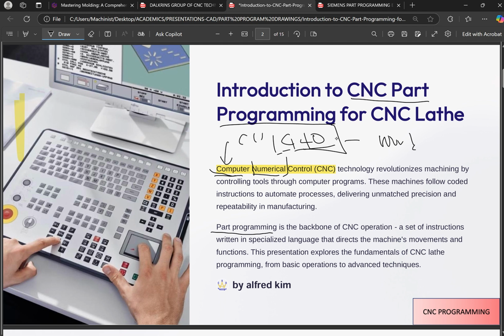Normally there is what is called the part program, which means you program a single component. If you have many parts together, you program a single component to give you that part. So that after machining the many parts, you can assemble them to give you an assemblage or sub-assemblies of the parts. So when you say part program, you are creating a set of instructions to control the machine table, or to allow the machine to automate the process of shaping the parts you want into desired shapes.